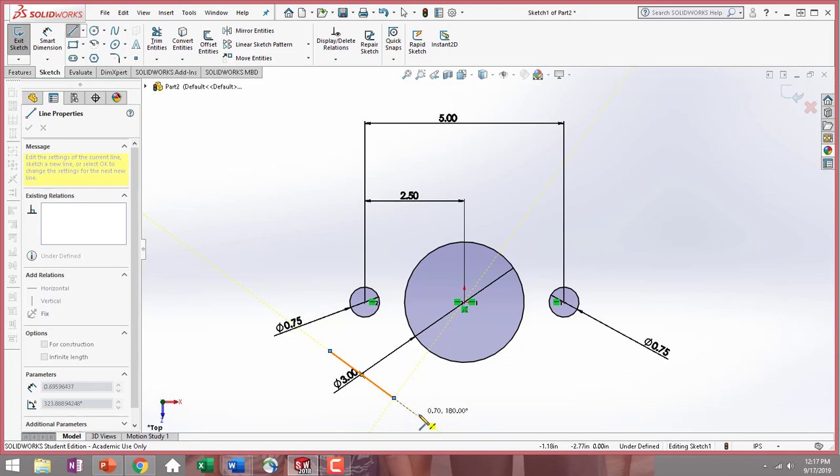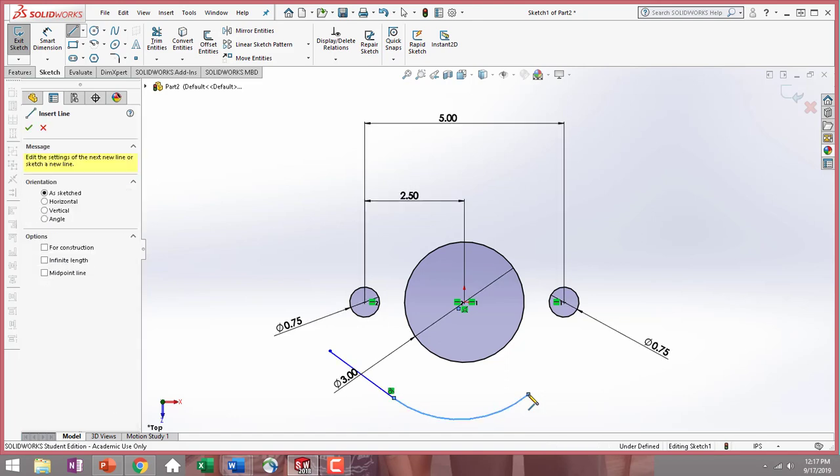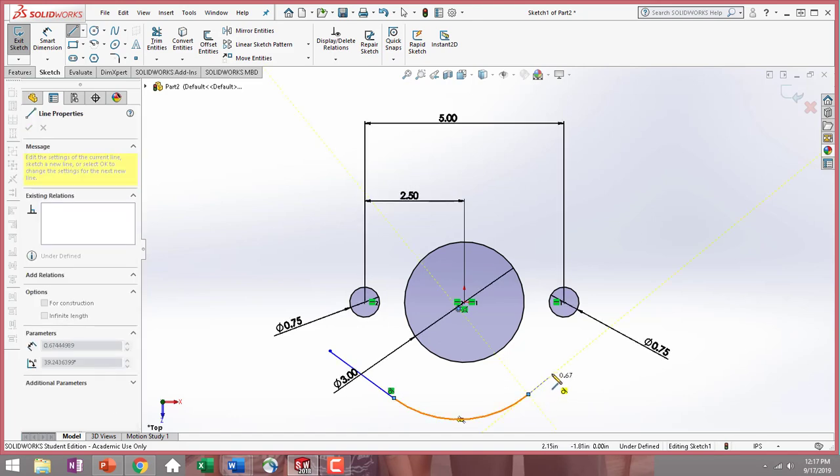Now instead of going back up to my toolbar and constantly switching between the line segment and then my arc, you'll notice that if you bring your pencil out for another straight line, you can bring it back to that endpoint and it now will have the arc for you. That will save you time so you're not constantly going to your sketch toolbar and selecting different icons. So go ahead, hit that down. It goes back to being a straight line. So draw out our next line segment.